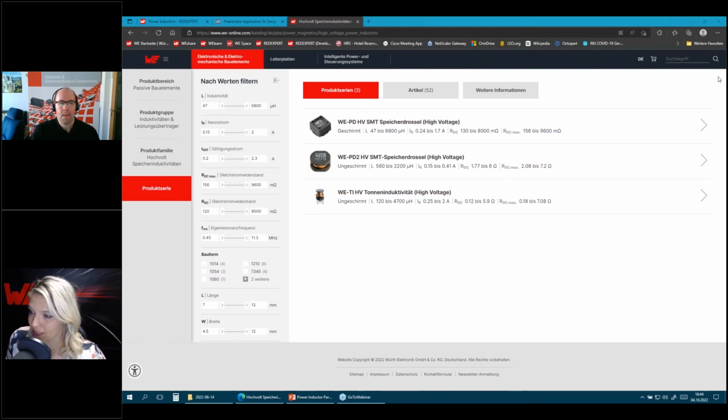Excellent, thank you. Our next question coming in, do core materials with soft saturation have temperature dependency? Yes, they have, but a much smaller dependency compared to the hard saturation component which I showed in the presentation, the PD series nickel zinc. They still have some minor effect, but it's nearly negligible.